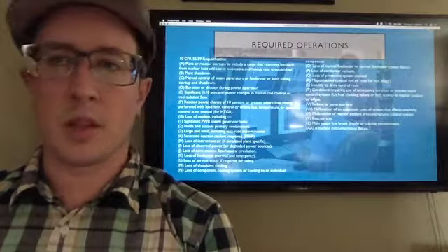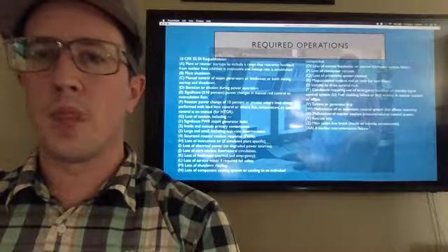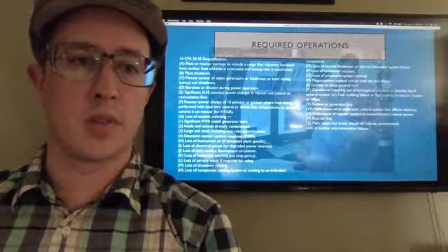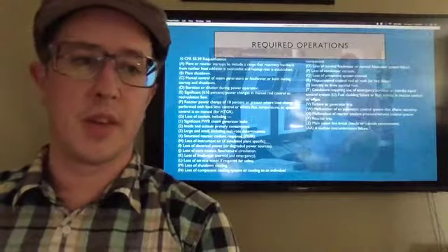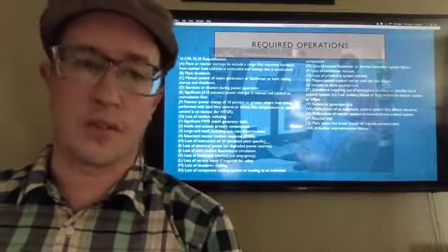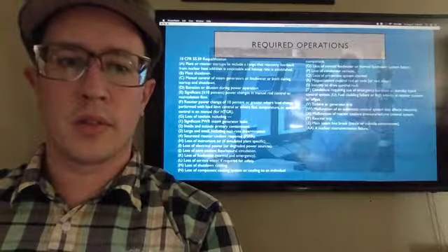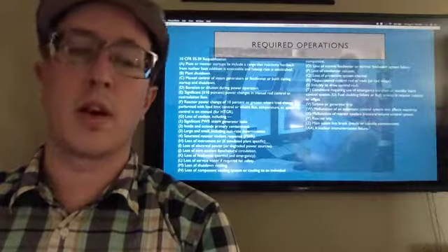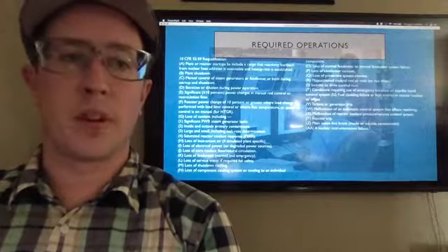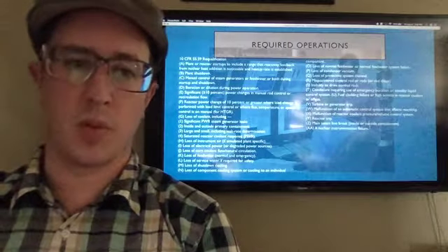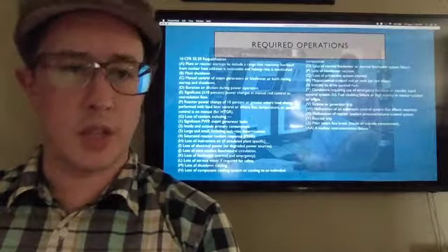This might include something like a plant startup, or plant shutdown, or heat up from a cold iron situation. There's also casualties included on this, such as a loss of coolant or a loss of vacuum casualty, a rod out of alignment. Of these items, the staff will pick 5 that the trainee must perform throughout their qualifications as part of their final certification testing.